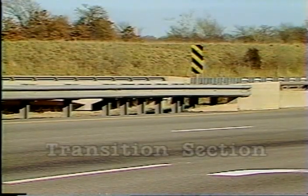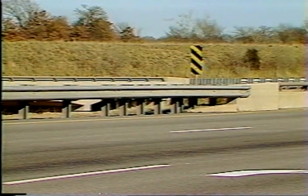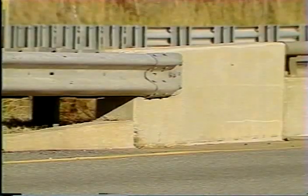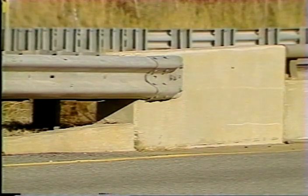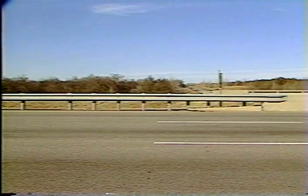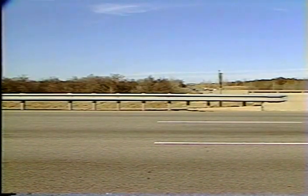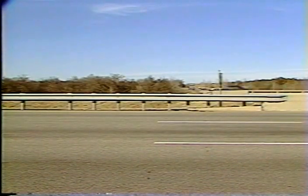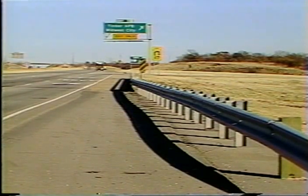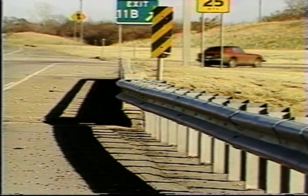The purpose of the transition section for most strong post systems is to provide a smooth, continuous change from one type of barrier system to another. This section may also function as either the upstream or downstream anchor of the system to a bridge. The transition section is designed to gradually increase in stiffness as it goes from the flexible guardrail to the rigid bridge rail. It is stiffest at the bridge end to allow less deflection at this critical point in the system. The stiffness prevents the impacting vehicle from forming a pocket in the guardrail and hitting the bridge end. The transition forms a smooth flare in the rail from the flexible section to the rigid section.